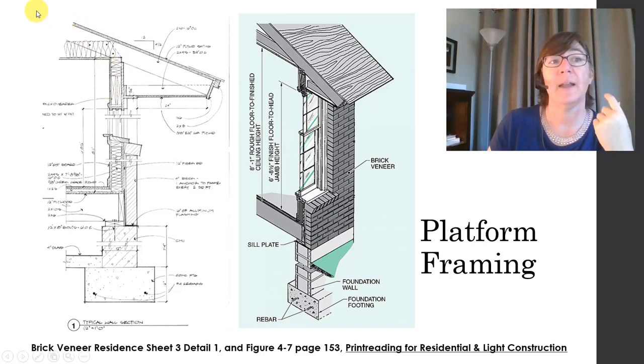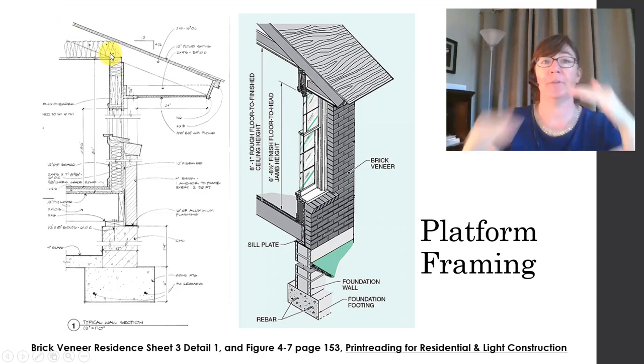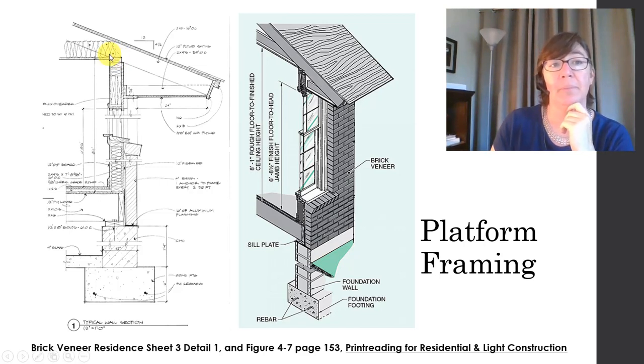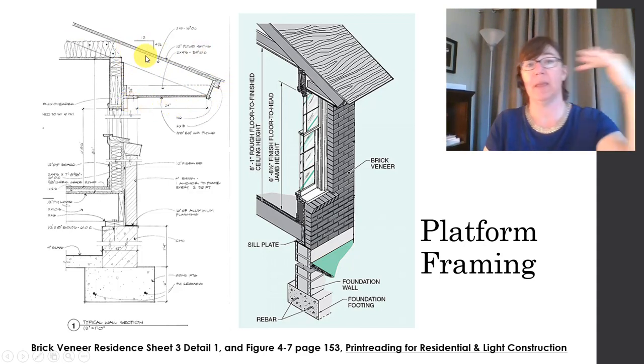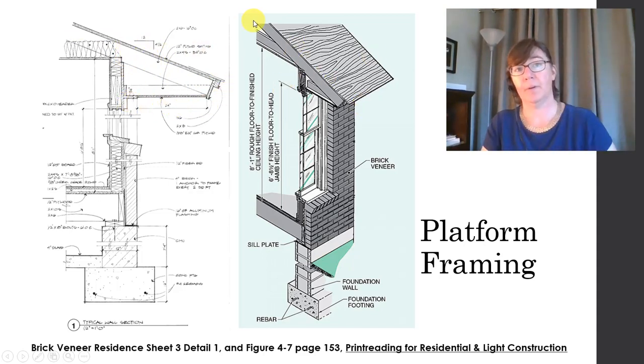Okay. And finally, here is our roof rafter coming down. And it rests on that top plate. They actually make a little notch, a little cut in the rafter so that it will bear straight down and flat on that double top plate. Here it is right here. This piece is called the eave. Remember the eave kind of sticks over. So here's our rafter. Okay.